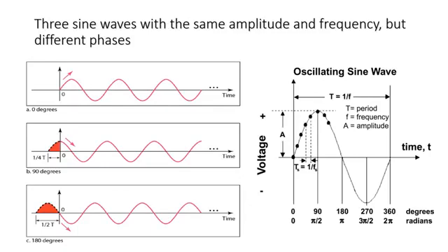Phase is the position of a point in time or an instant on a waveform cycle. A complete cycle is defined as an interval required for the waveform to return to its arbitrary initial value. The graph to the right shows how one cycle constitutes 360 degrees of phase. The graph also shows how phase is sometimes expressed in radians, where 1 radian of phase equals approximately 57.3 degrees. Phase can also be an expression of relative displacement between two corresponding features, for example, peaks or zero crossings of two waveforms having the same frequency.